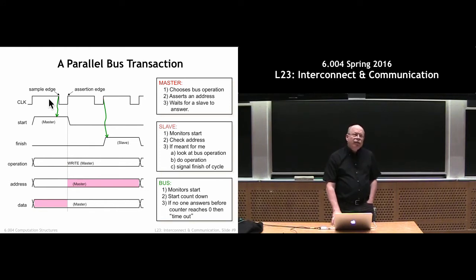Then the bus had some responsibilities. Its job was to keep track of requests that were being satisfied by nobody, and to be the default slave that would assert some sort of response code and say, I'm done. There was usually an error code it put on the bus saying, nobody answered, so this is your "nobody was here" signal.